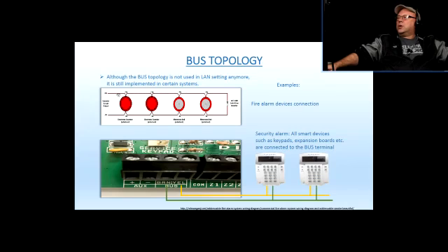Then the system would only see a closed loop with something called an end-of-line resistor on it. It has to have a certain resistance that the system wants to see. If the zone sees that resistance, it thinks everything is okay. Now there could be two conditions. If the line is broken, the system is going to see an infinite resistance at its point, because there will be just the resistance of the air between them. So this is more or less considered infinite resistance for this purpose.